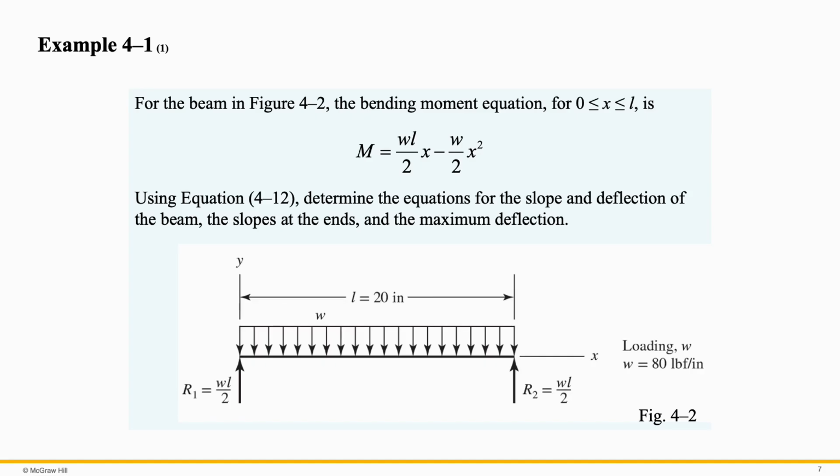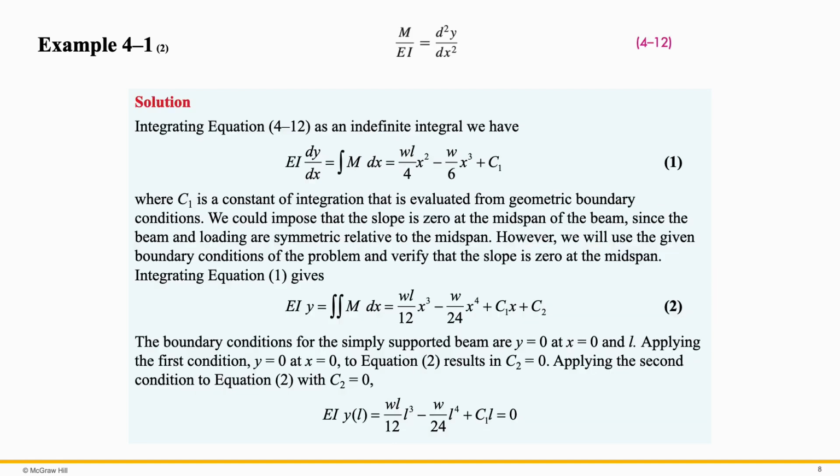You can easily determine the moment function here as a function of x. It is also provided in the problem statement, but it is easy to determine since we know the distributed load intensity function here, w. For this reason, we can easily construct the moment function. So this is our moment function.